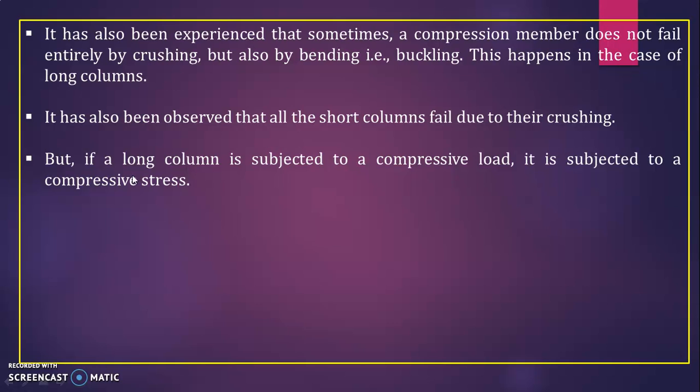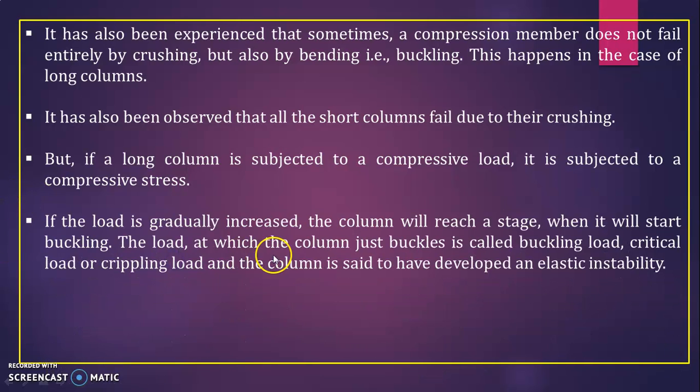But if a long column is subjected to a compressive load, it is subjected to a compressive stress. If the load is gradually increased, the column will reach a stage when it will start buckling. The load at which the column just buckles is called the buckling load, critical load or crippling load, and the column is said to have developed an elastic instability.